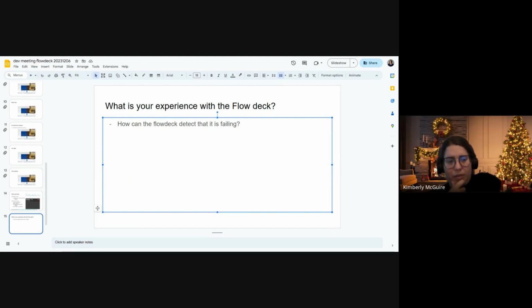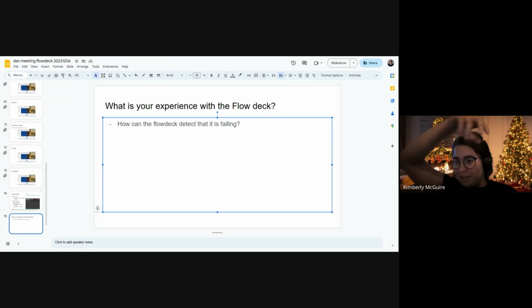Yeah, that's a very good question. The thing is that you have the range sensor to consider. Of course, it will get a very big jump, and the Crazyflie would respond to that. Other than that, even if you would just fly over a table by itself, and maybe you disable the range being determined only by the range sensor, or maybe you use the lighthouse but still the flow deck, if you would fly over a table and just look at the camera footage, then at one point you just have a very quick change.